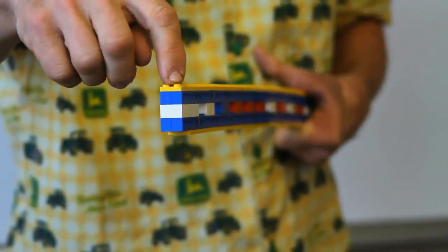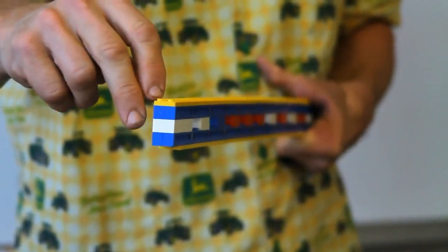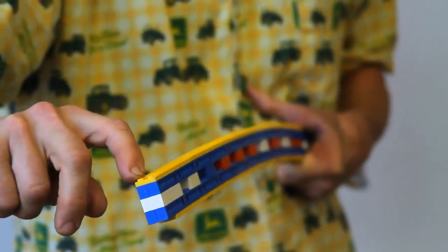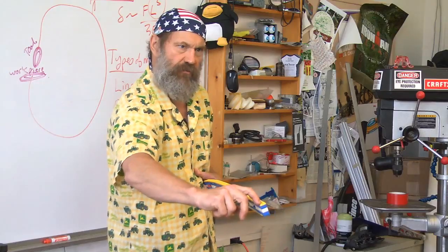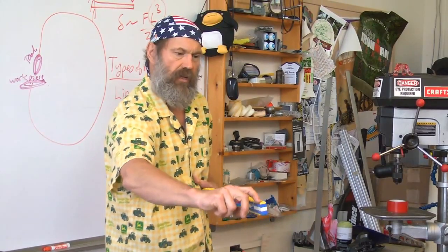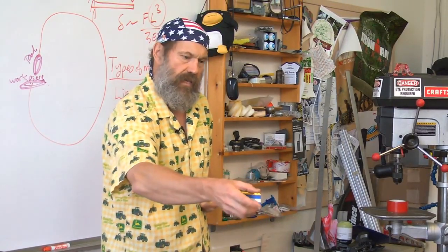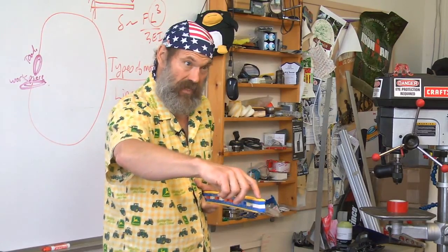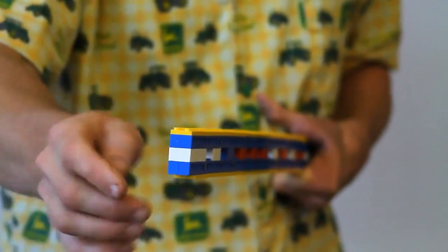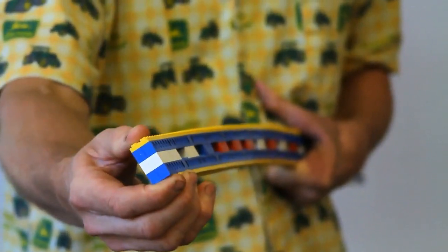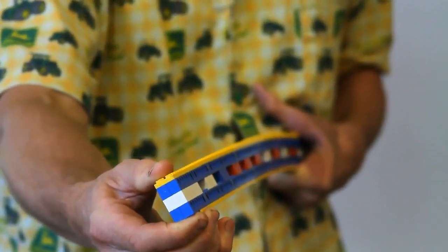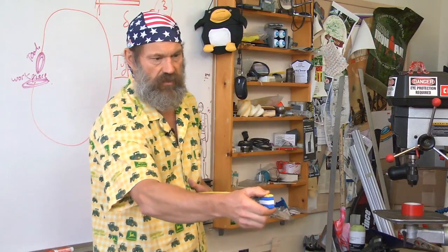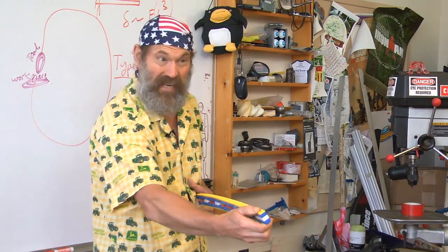What happens when this beam is loaded symmetrically? But if I load it off-center, watch what happens. See how it twists? A very common failure mode in a structure is if you take a beam and it's not loaded through what's called the shear center of the beam, you'll get a torsion which can then cause it to buckle and fail. So you have to be very, very careful how you actually load beams to ensure that they don't have one of these torsional instabilities in bending.